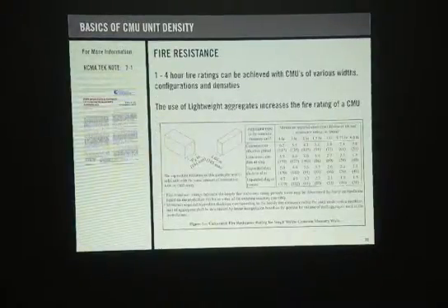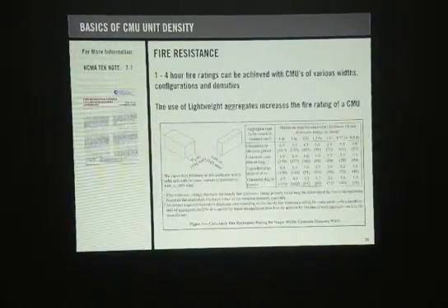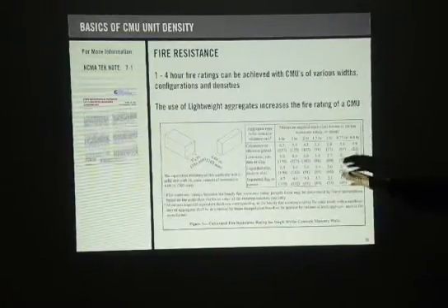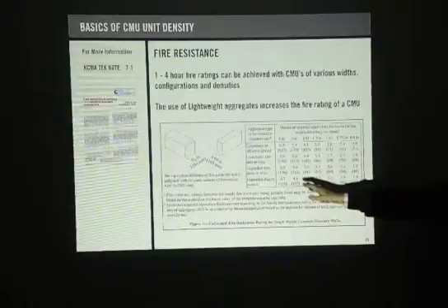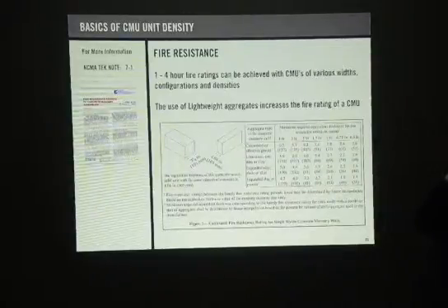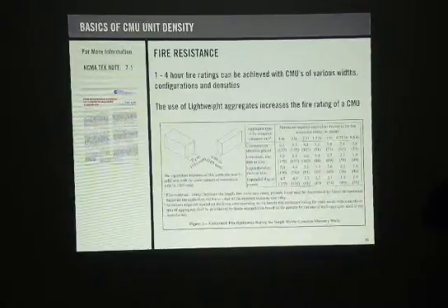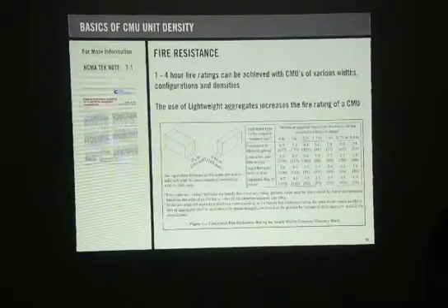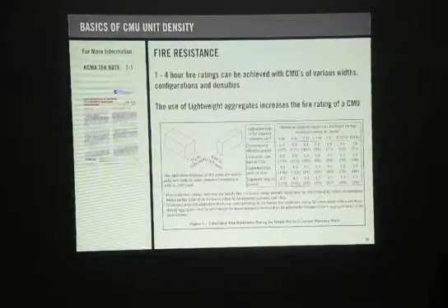As far as fire resistance, we mentioned earlier, Bijan had a great question when it came to fire resistance. He just didn't know it. But he asked about fully grouted block. Is it an advantage to have fully grouted block? Well, for fire resistance it is, because with any of the three weights that we mentioned, lightweight, medium weight, normal weight, you can get, with a fully grouted block, a 4-hour fire rating. You can't get any better than that, okay?